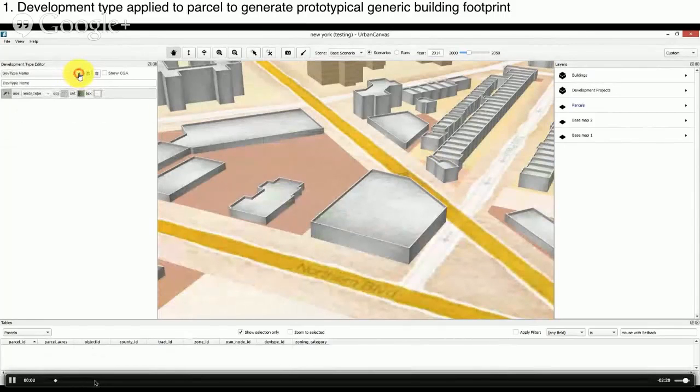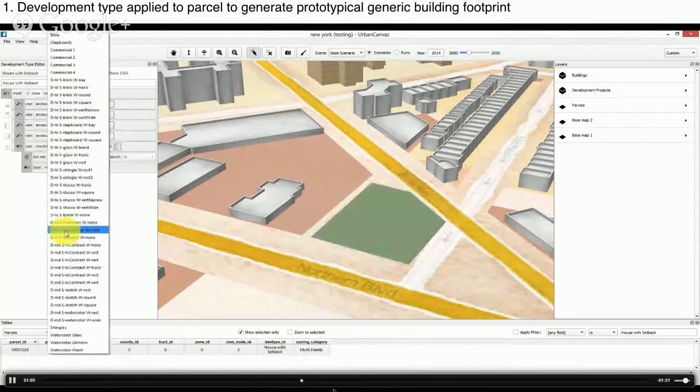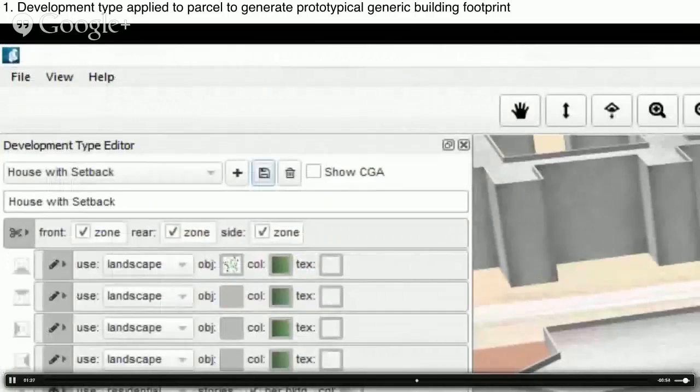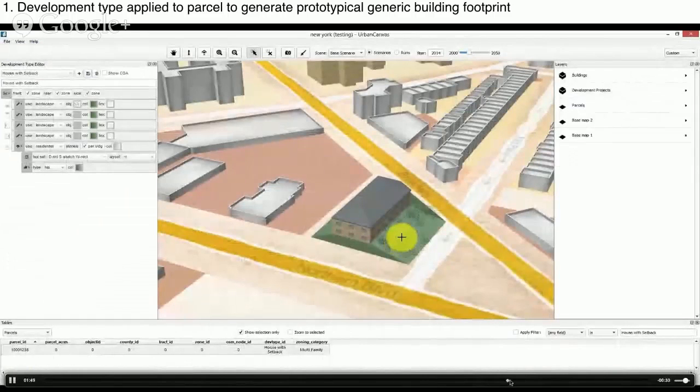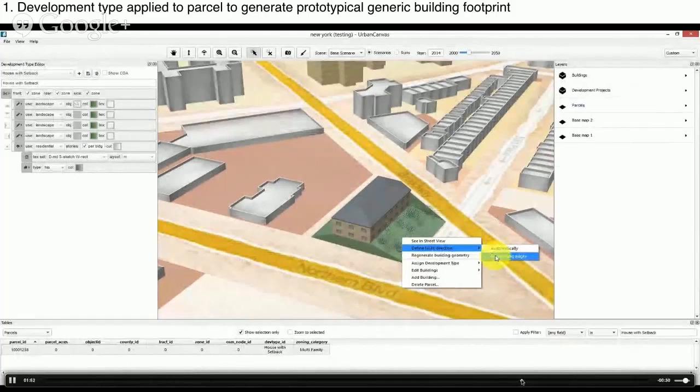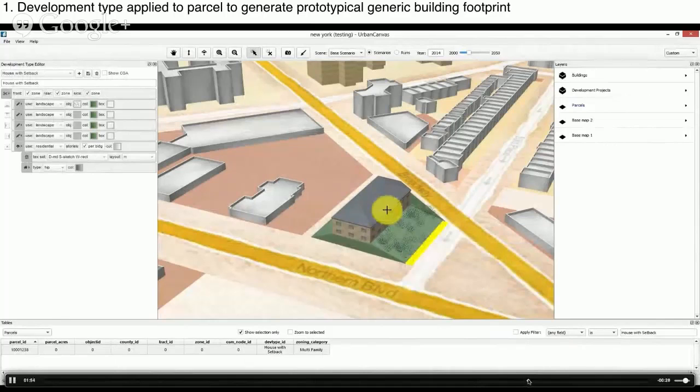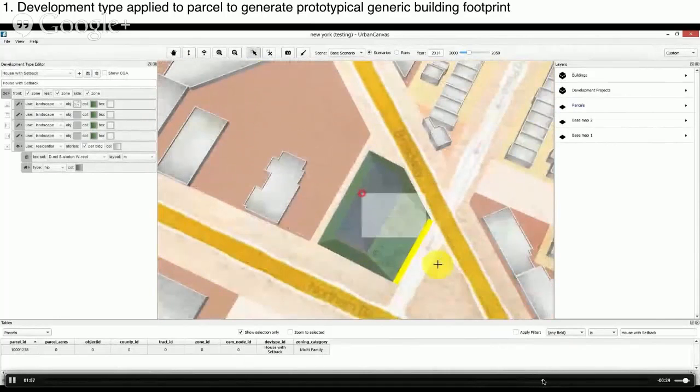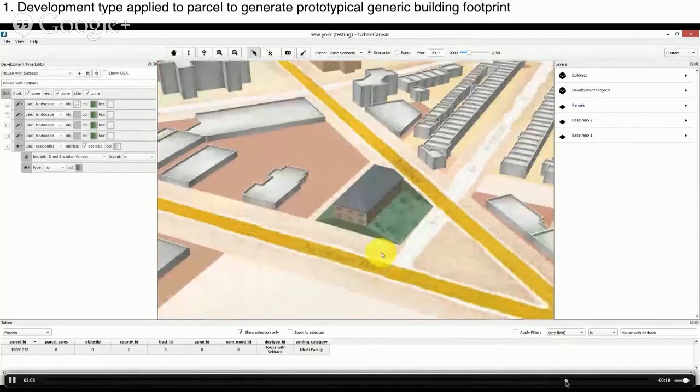The front is selected automatically, mostly by UrbanCanvas, but you can also manually assign a frontage. So here, when I assign the front, you see the trees appear in the front that UrbanCanvas picked up automatically. But then I right-click on it and say I want to manually select a frontage. Especially on corner sites, you might need to do this more often when you need to know what your frontage is. So here, when I select the new frontage, the front appears in the direction I just selected.